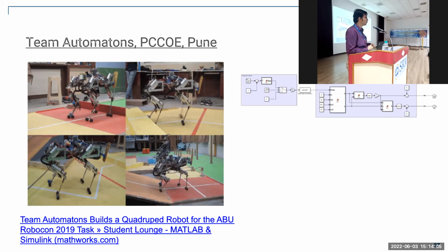So the quadruped's foot, how it is going to move. Typically, we can assume that it moves in a semi-parabola. If you assume that, you can build an algorithm which can back calculate, for that movement, how the hip angles will vary, how the joint angles will vary. So this is the basic algorithm that they designed for that.